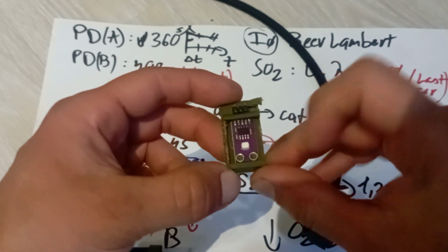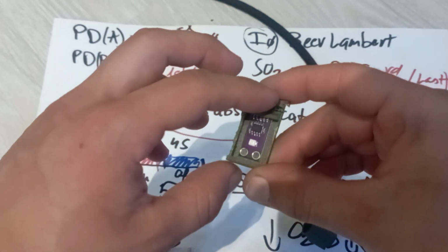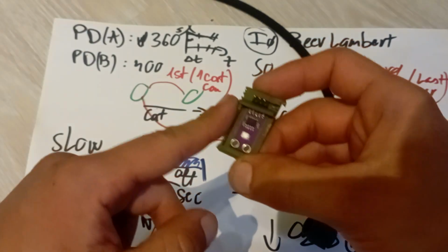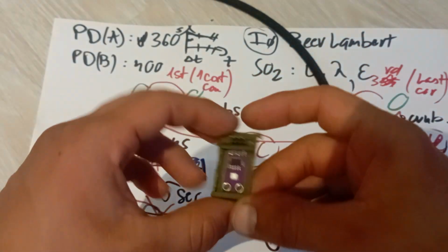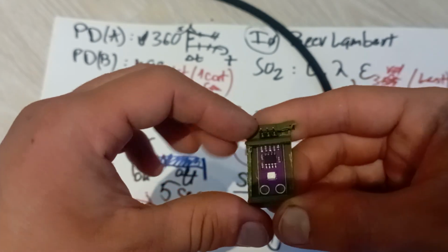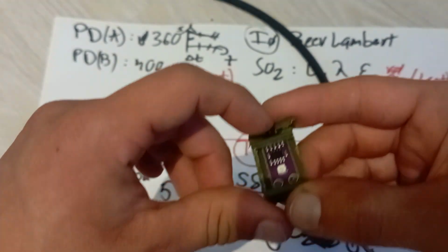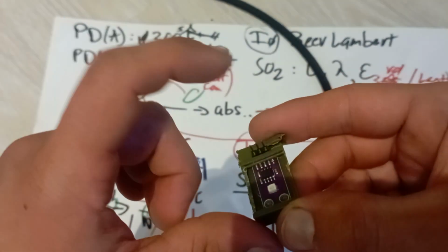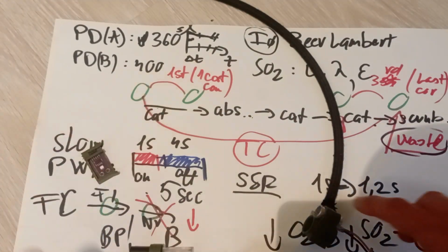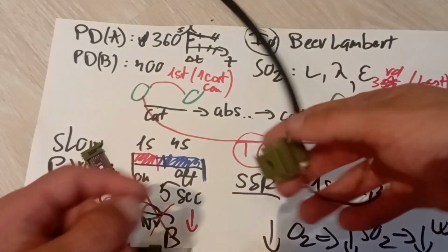This is the photodiode there. This is the GUVA, I think it's 12SD or something like that. This is a photo board especially made for absorbing UV lights. And this has a 3-pin connector. This is the power, mid is the ground, and the third is the signal. This puts out some voltage that we can read on the Arduino, or ESP32 if you will.